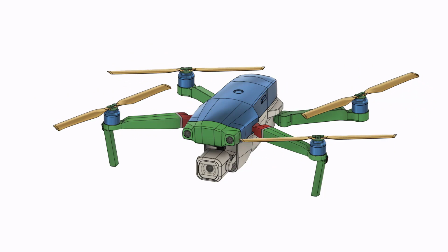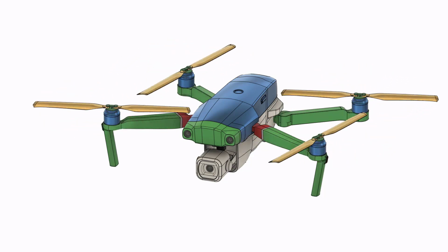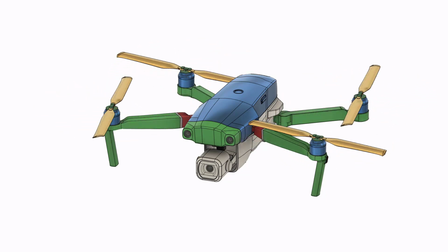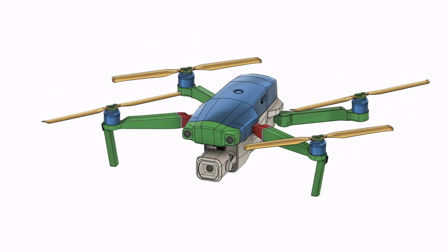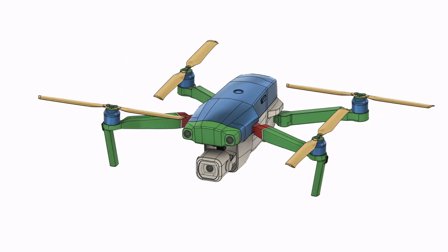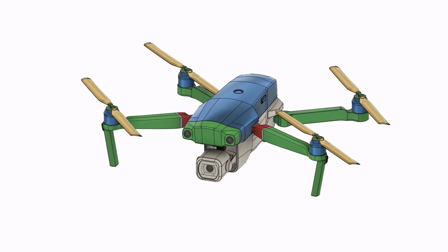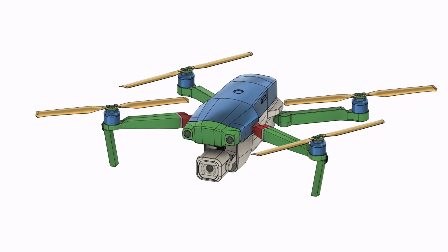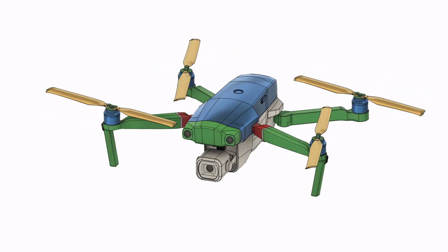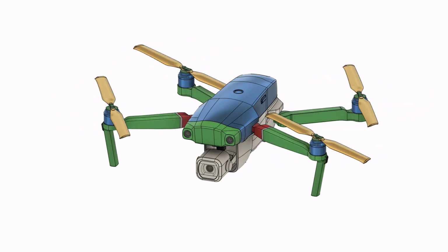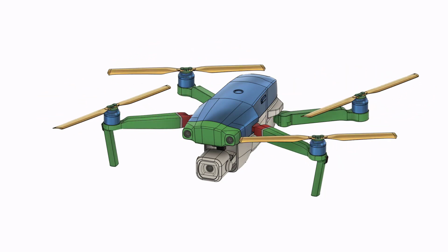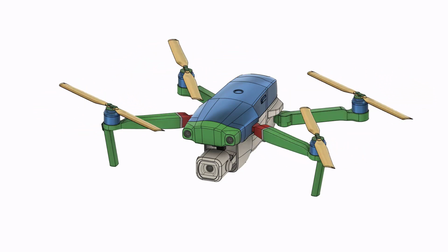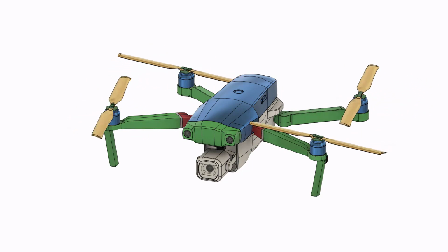Torque is the twisting force produced by the motors or propellers. It's crucial for rotational movements. To initiate a turn, adjusting the thrust from different propellers creates torque that results in yawing. Torque is what allows the quadcopter to rotate. The quadcopter has 4 motors rotating with specific angular velocities, and the previously discussed motions are achieved by regulating these angular velocities.